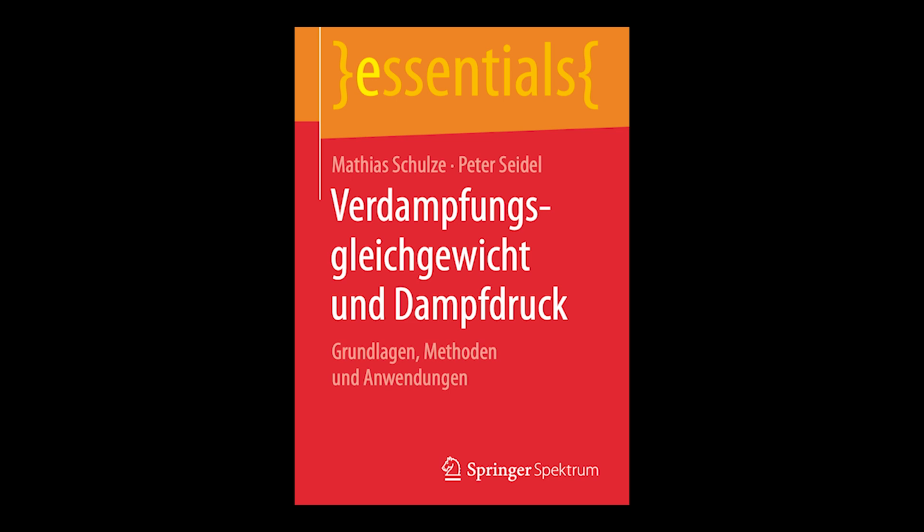This device was revolutionary because it solved the problem of the sample distilling away. Its design is truly ingenious. The sample liquid is placed in a closed, heated vessel. This vessel is coupled to an auxiliary U-tube manometer, and critically, this auxiliary manometer is filled with the sample liquid itself, separating the sample from the external, high-precision main manometer.